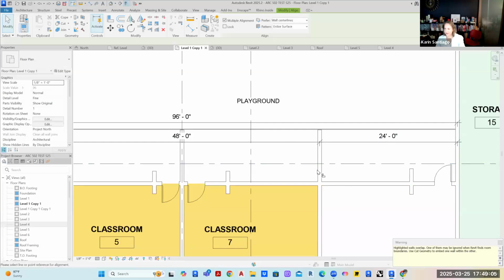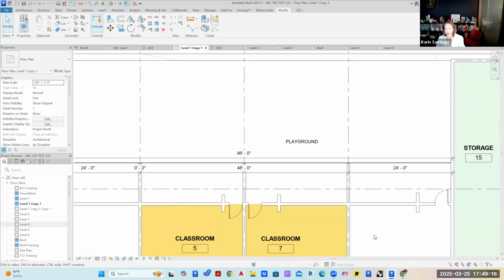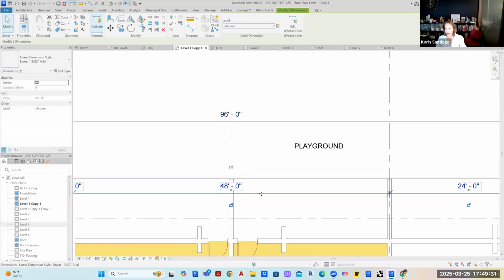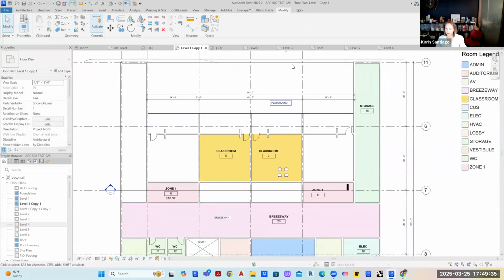So I'm trying to align these to the center right now. And you can lock them. I never do that. Don't lock things, because sometimes what happens is that, yes, you may want your walls to move with your grid, but sometimes you end up over constraining things, and then later maybe you forget, and then things get moved altogether, which is not ideal. So as a general rule, I try not to lock my grids. So, just something to think about.